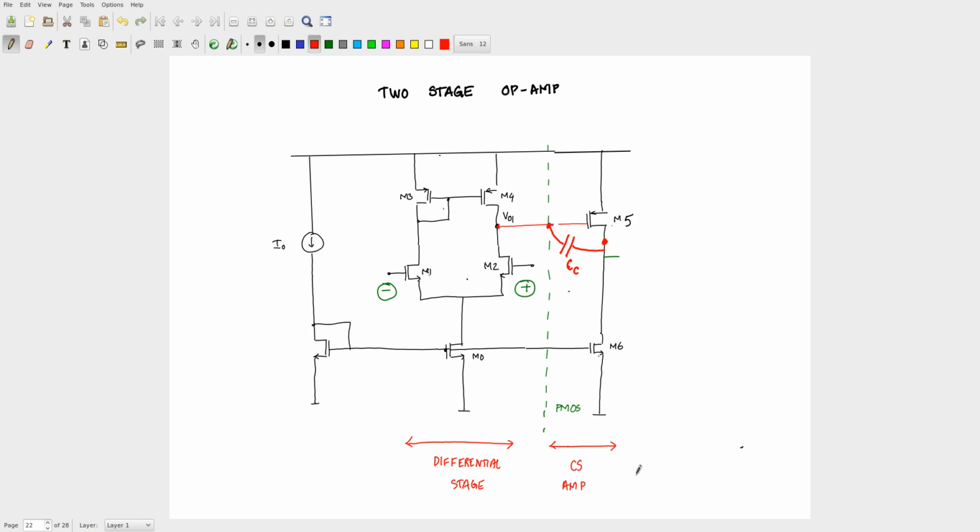All right. Now, what is the output of the common source amplifier? Is it high or low impedance? It is high, right? Because in the ideal case, it will only be the resistor R0 of the transistor, right? So, for an ideal op amp, what do you want? You want low output impedance. So, what can you do to this in order to get low output impedance? Exactly, you just buffer it. So, what kind of buffer should you put?